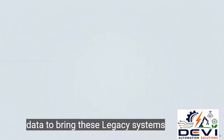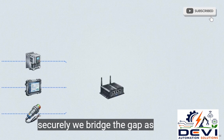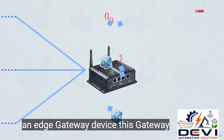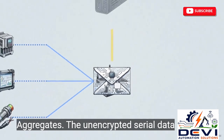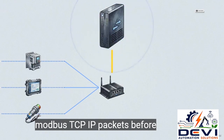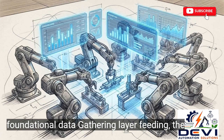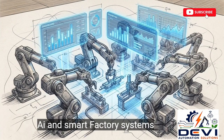To bring these legacy systems into modern Industry 4.0 environments securely, we bridge the gap. As shown in this layout, legacy Modbus RTU serial networks are fed directly into an edge gateway device. This gateway aggregates the unencrypted serial data, translates it, and wraps it into encrypted Modbus TCP/IP packets before sending it to cloud servers. This integration positions Modbus as the foundational data gathering layer, feeding the specialized information required by modern AI and smart factory systems.